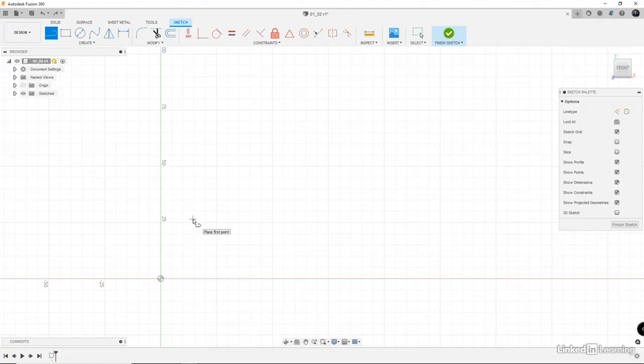Now, let's go ahead and create a line. Let's reference something here, and let's come up and give it a length of 50 and an angle of 45. Hit enter, and it created that line at a 45-degree angle. It also created a construction line right here that it's referencing that 45 degrees from. Let's hit the L on the keyboard again, launch the line tool.